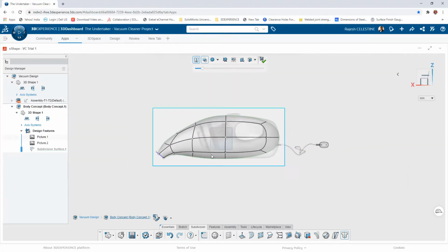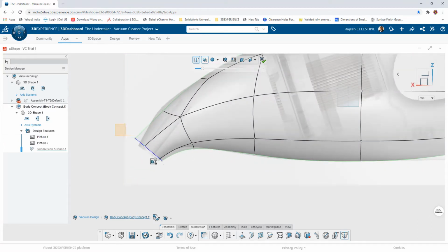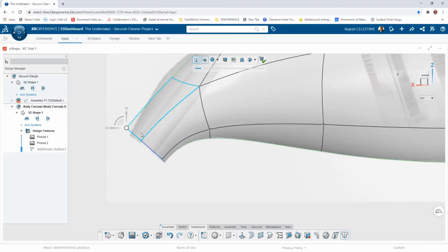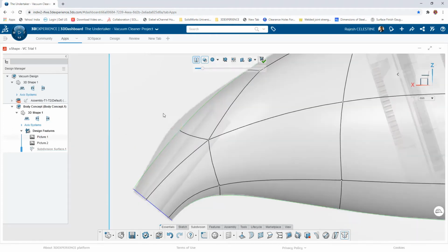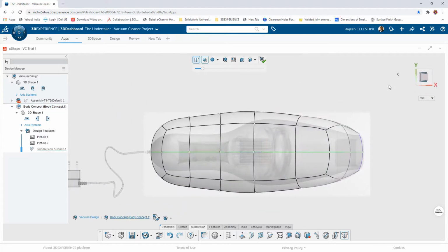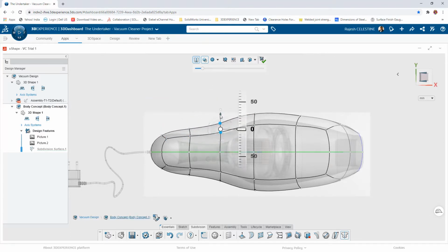Dragging the entities onto the sketch completes my profile on the portion of the suction mouth. Refining my model helps me to complete the portion on the suction mouth. Now, having completed the portion of my suction mouth, I would like to refine my geometry on the portion of the handle. Before this, to refine my geometry, I would like to add additional loops and position them in the top view.